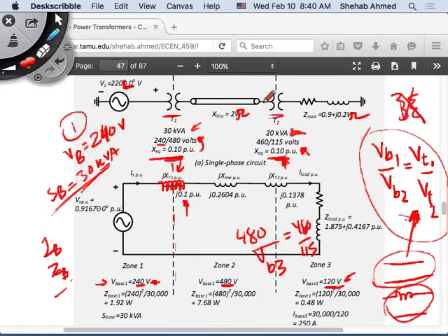Okay, so that's done. And now I need to look at its impedance. Its impedance was calculated on which base values? A certain power base and a certain voltage base. The power base and voltage bases are different than what I've chosen in my system. So I have to do a change of base for this impedance. So this impedance will change values, and we'll apply the equation that we just saw before. So this is not 0.1, it's going to be 0.137, and so on. We'll look at the math for this right now.